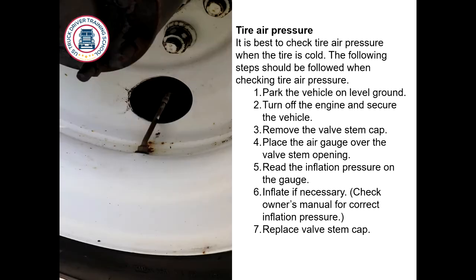Tire pressure. It's best to check tire pressure when the tire is cold. The following steps should be followed when checking the air pressure. Park the vehicle on level ground, turn off the engine, secure the vehicle.